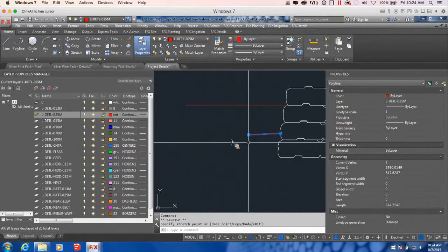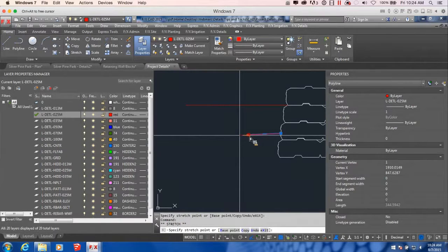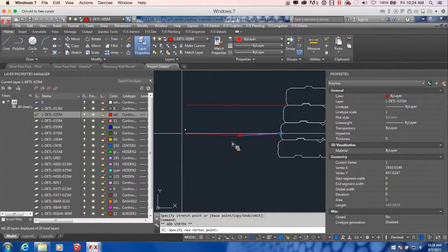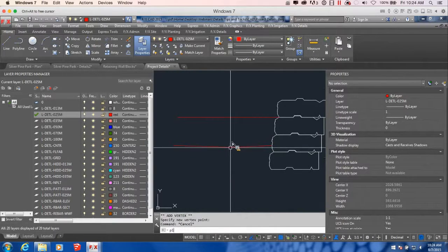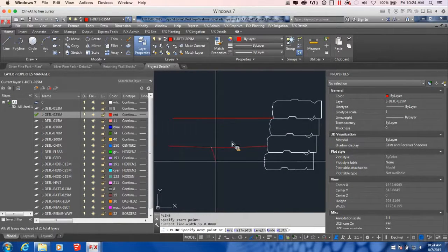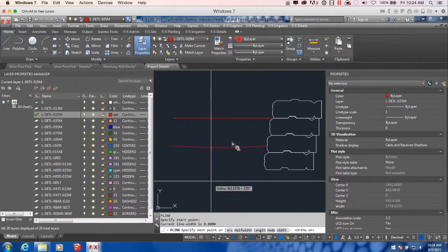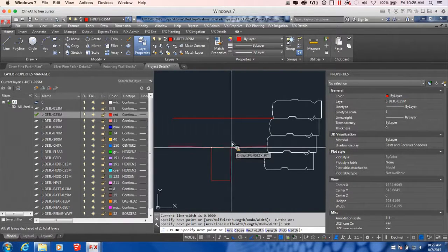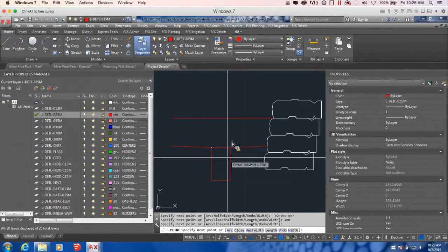Slope that just a little bit, about a foot away. Great, and add a vertex and slope that back up. And then just draw my drainage. I'm being a little bit loose in this one just because it's a webinar. So we'll pull in my drainage, obviously you'll be a little bit more precise. My drain pipe's about 150, so 200 wide drainage trench should be good for this.